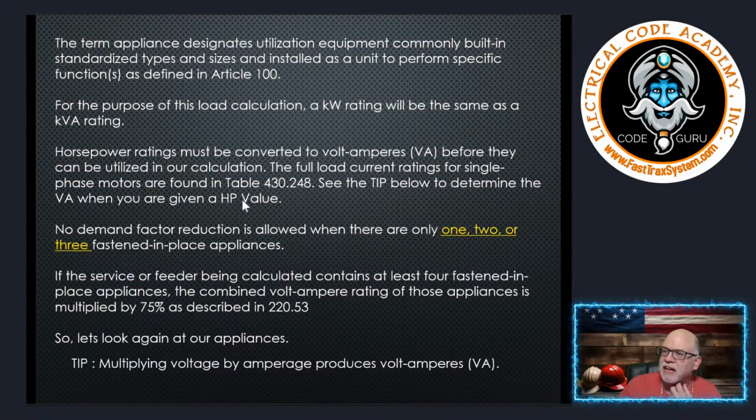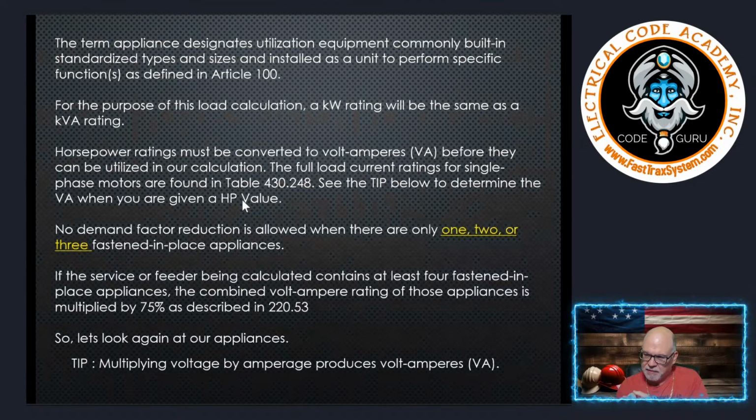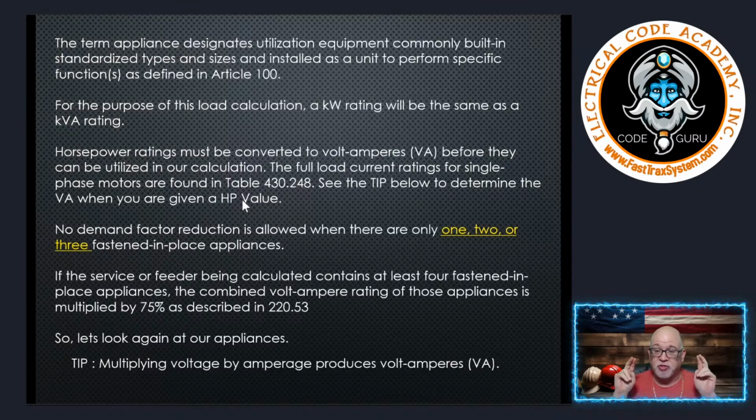Okay, now the first thing that we also want to remember is that typically in residential calculations like this, anything with a HP or horsepower rating is a motor. But a trash compactor, dishwasher, things like that, we're not considering those as motors. And that's important later when we're looking for the largest motor in the dwelling. Okay, so we want to make sure that you understand that when you go looking for the largest motor later, you definitely want to make sure that you're looking for a true motor.